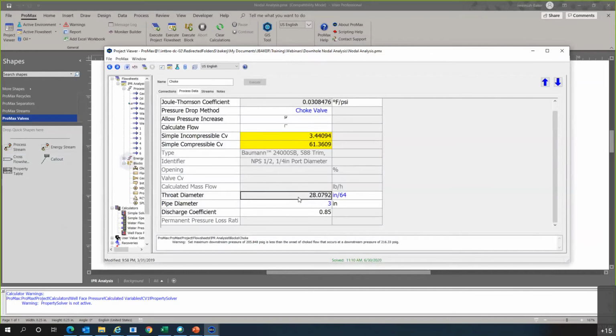So once again, this is the point where hopefully, when you do your real case, that value check is very close to what it should be. If it's not, then maybe we need to go in and look to see, do we need to use a different IPR correlation? Do we need to get an updated sample? Maybe we're using a PVT that was taken 4 years ago, but we can use a backsplitted sample that was taken 6 months ago. That probably is a bit more accurate to the actual composition going through here.